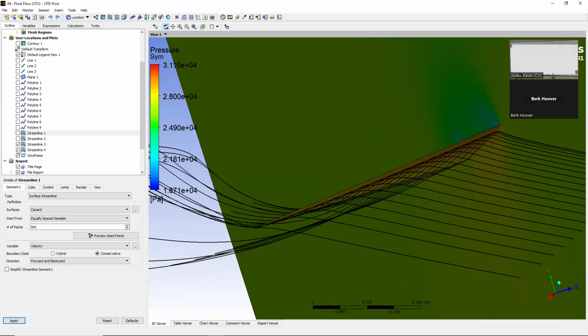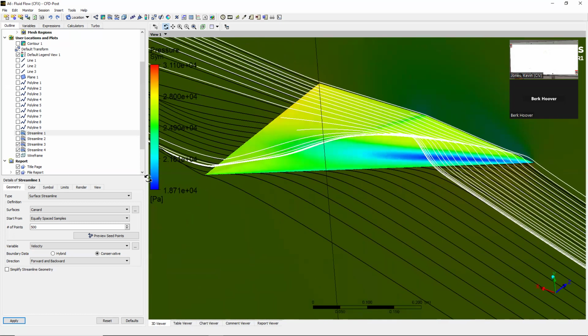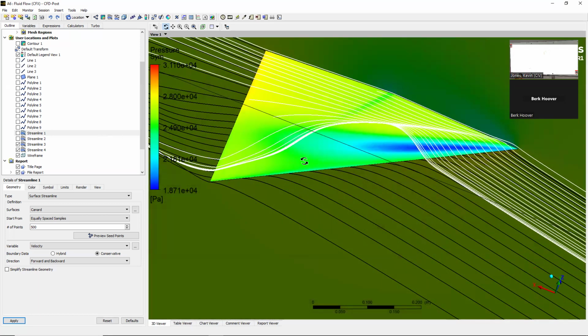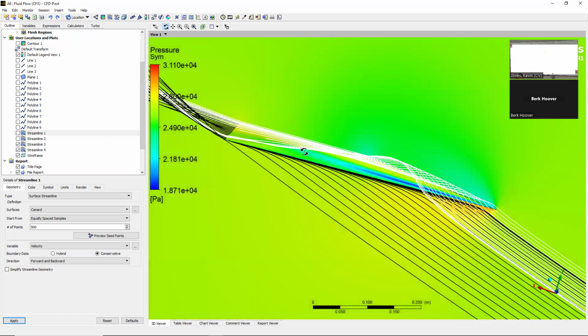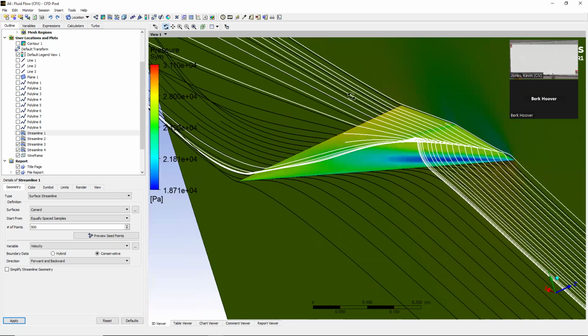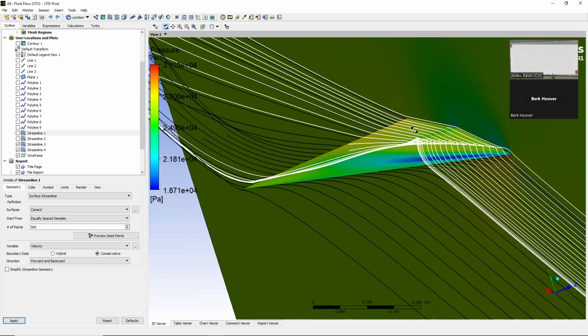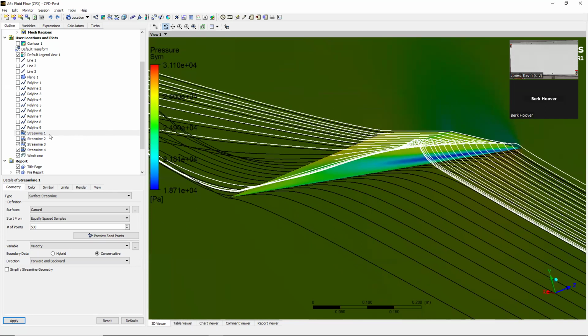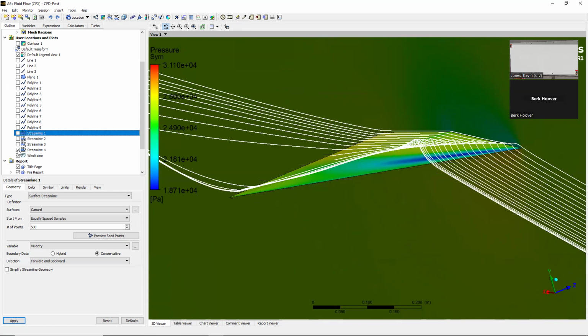Let's see, I think I have one other, kind of seeded on the exterior of the vortex. So this one starts to show you where you're reattached again on the center portion of the wing. So probably if you got up to about a 30-degree angle of attack, you would see this start to fail here. You'd start to see a separated pocket in the middle.